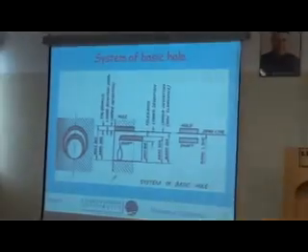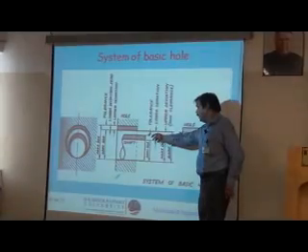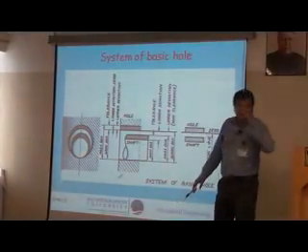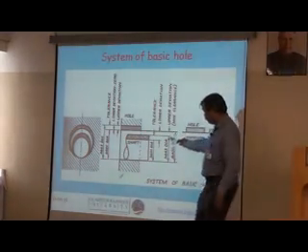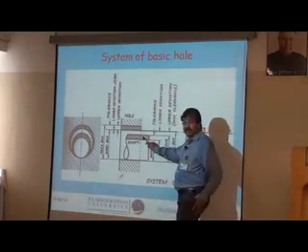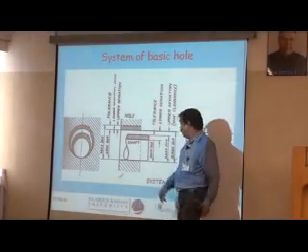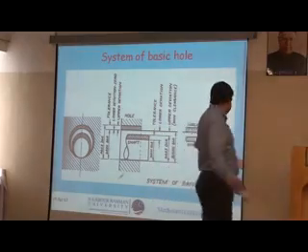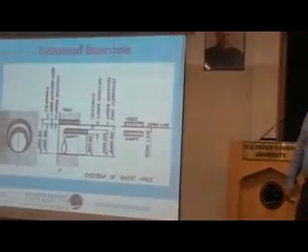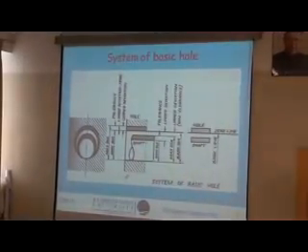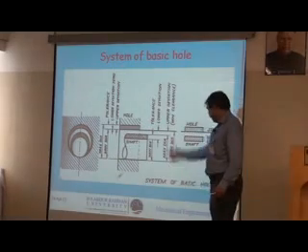Next slide please. Now you have a hole. What is shown in crossed lines is the tolerance permitted on the shaft. This is the tolerance permitted on the hole. Now what type of fit will you get if you have such a shaft and such a hole? It will be a clearance fit. Obviously you will get a clearance.